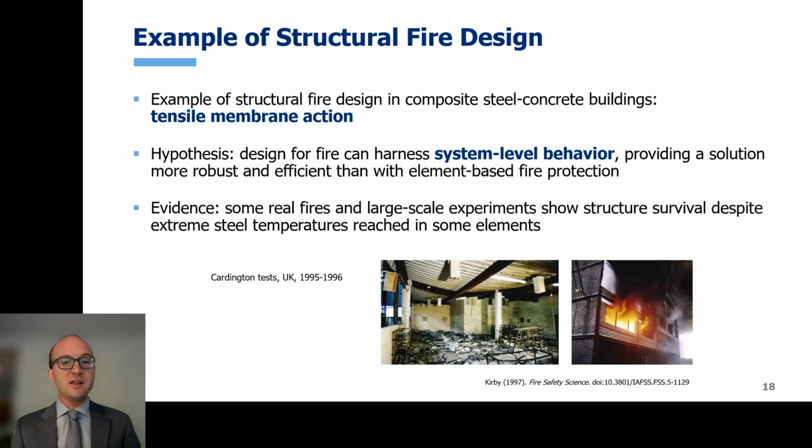In the 1990s, there were a series of very important experiments for the field of structural fire engineering conducted by the BRE in the UK. They are referred to as the Cardington fire tests. And in these experiments, it was notably observed that some structures survived, meaning they remained stable, throughout a fire, even with some steel beams being unprotected.